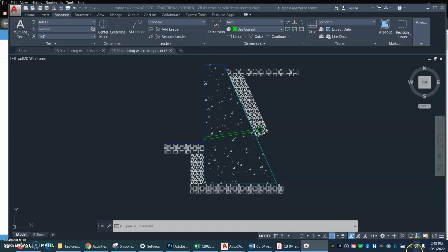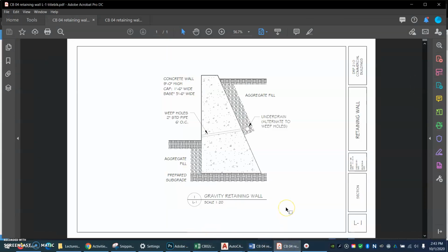Now let's put text on our drawing. And if I may give you some advice, when you are putting text on and you don't have to worry about dimensioning, it really is easier to go to paper space and put it on there, because you don't have to worry about scaling it. Do you remember how high text is? Yep, it's all 1/8 of an inch high, with the exception of this title text, that'll be 1/4 of an inch high. Everything else, 1/8 of an inch.